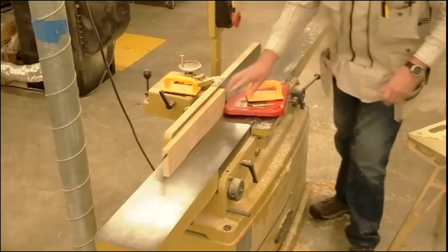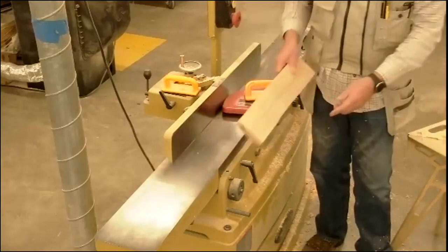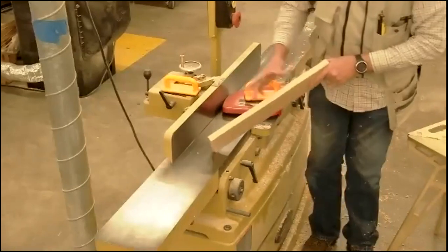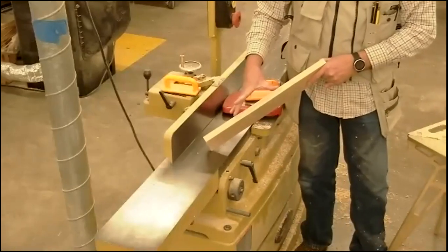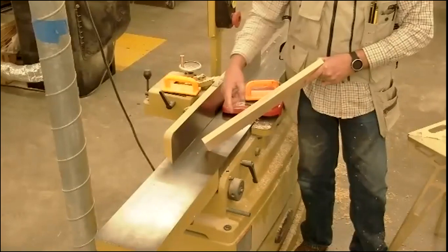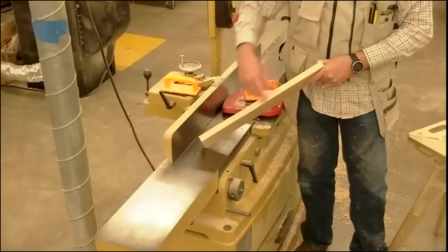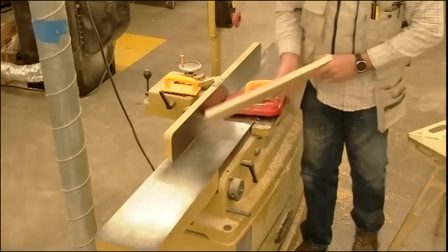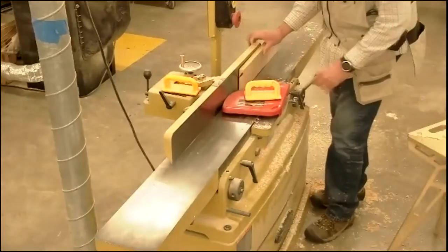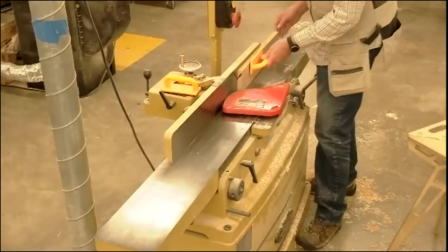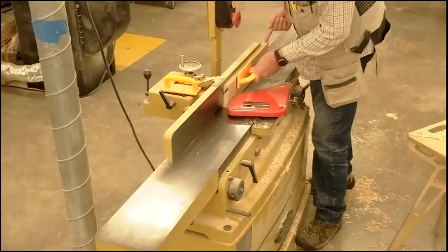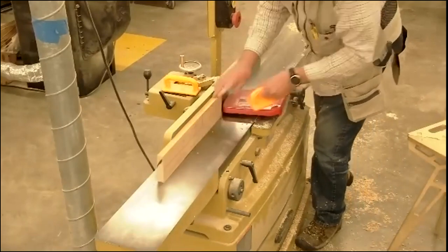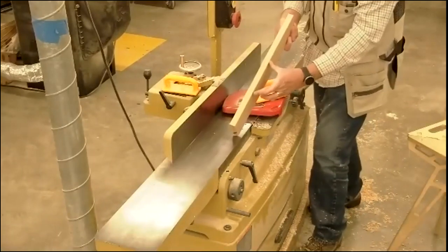All right, so you should have been able to hear that it touched at each end but not in the center. You can see that our non-jointed surface that hasn't been hit yet is about this long, okay? Going from about right here to right here. My pencil marks are telling me for sure. So I got this much done, I got this much done. Let's run it again, listen to the jointer and see if we can tell when it's done. Now we've got about this much left to do.